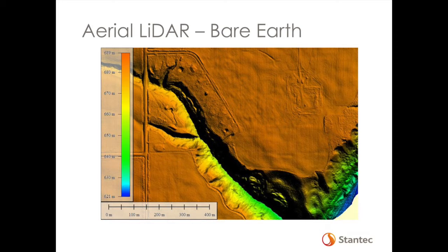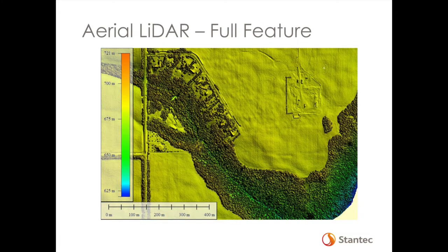They might just get a contour plan. So going back to the raw data is really where the importance lies in figuring out what you can do with this. If you look at a full feature data set, this is an image file of a LiDAR data set. It includes vegetation, so you can see where all the dense canopy is down in a ravine. You can make out a little tree line here. You can make out some buildings, some small buildings inside here. It takes everything, including terrain, and puts it into a surface. So it's very valuable for tracing extensive tree lines and extensive vegetation.